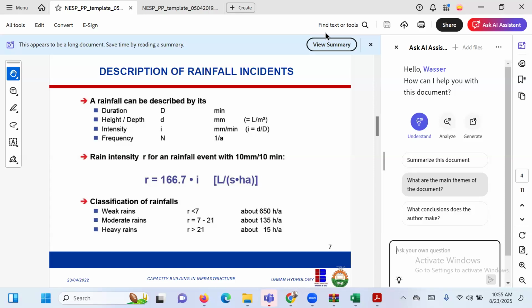But when you're talking about big cities, center of towns, of most cities, they use very high safety factors, and that's why most of them are underground, not surface. Because underground, they can build 2-meter diameter pipe, they can build 1.5-meter diameter pipe that can hold the entire storm water in the city up to a 10 years flood. Very, very important to understand when and how to use the return period of your rainfall.